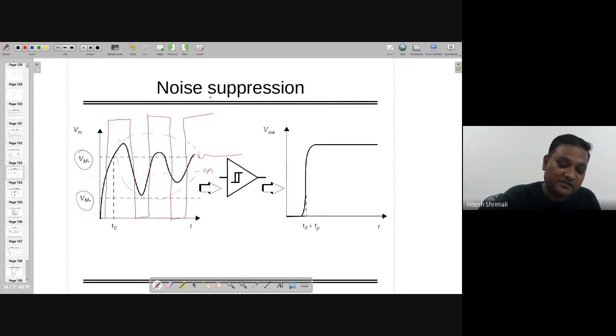It means if there is a small amount of noise, that noise will be amplified, because of the common source amplifier or the class AB push-pull amplifier, that's the characteristic of my inverter. So if I am around the switching threshold voltage, that was the last example of your first assignment, where I asked you to do this, where you have given VDD by 2 and some small input that was inverted and getting amplified.